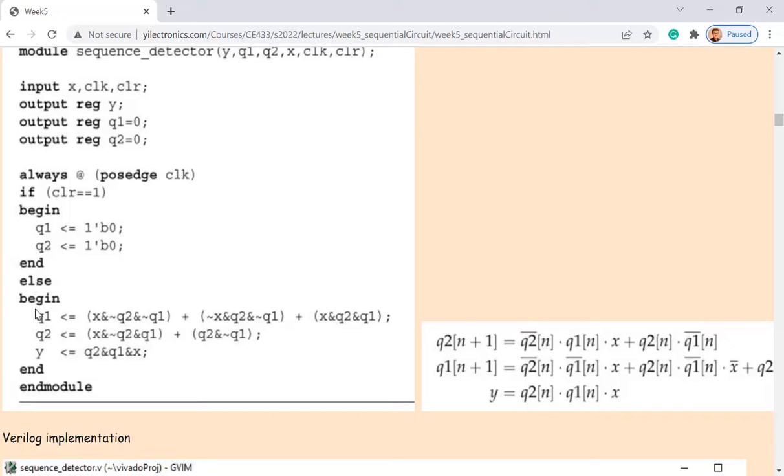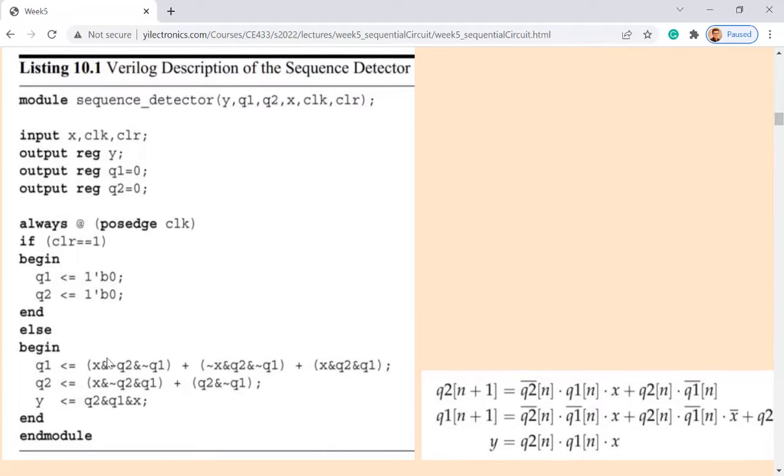So these are the final outputs, and these outputs are being assigned by these signal lines or logic equations using what's the name of this assignment? Non-blocking. So they have to be registered, the reg tag over here.